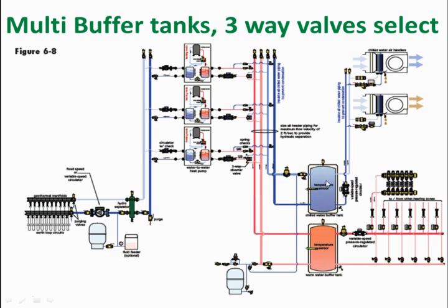What else have we put in here? Just some good commonsensical piping application tips there, about getting your pipe size, so you make sure you've got that 2 feet per second to make sure you get good air removal out of that piping. I know some of these are probably getting a little tricky for you guys to read as I get more and more stuff in the drawings. The print and the size of everything gets smaller, but again, these are all in the Hydronics 9 issues, so pull them out when you get a chance.